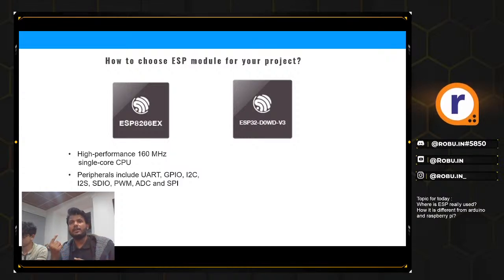It is basically if I need Wi-Fi, and secondly if I need a camera or a better processing speed, then Raspberry Pi you can go. But if you need just this much, you might question me, Prathamesh, we can also buy a Raspberry Pi, but the cost of a Raspberry Pi is way more when you compare it to an ESP32. Also, ESP32 has an inbuilt Bluetooth system along with the Wi-Fi. So if you want Bluetooth, you can also use it too.